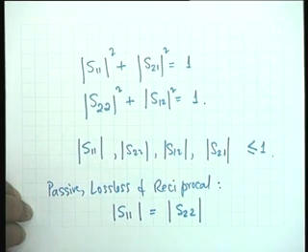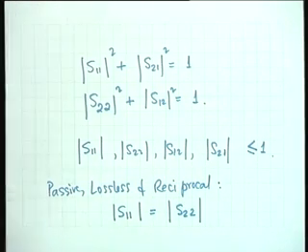Isn't that right? That is, the reflection coefficient magnitude at port number 1 and at port number 2 should be equal. Agree? These are the various interesting properties of the scattering matrix parameters.